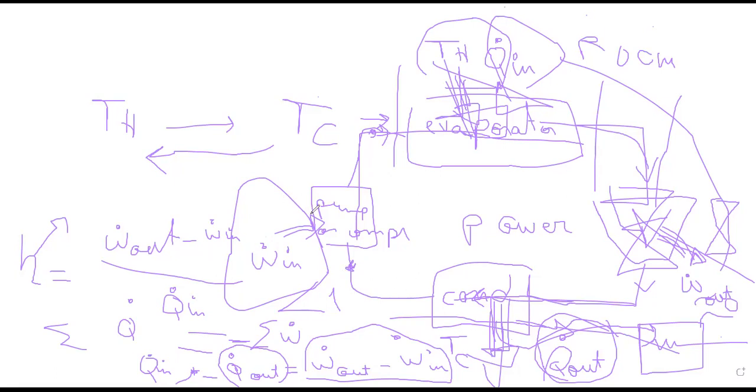So you were able to reject heat from your inner space, which is relatively cooler than your outer space, because you supplied electrical work. Now, in case of winter, you reverse the operation of the system. Your room will be on the condenser side. So you will reject heat into your room, while you take heat from the outer environment.